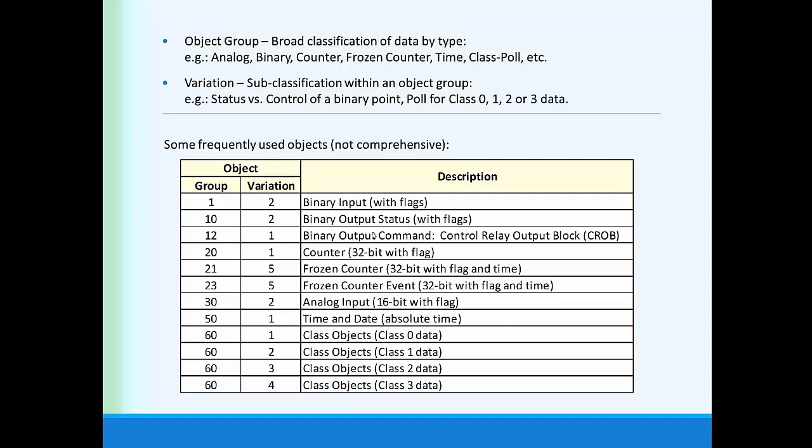So what's a class 0 poll? An outstation or a meter or an IED will have, basically, a meter does kilowatt hours. A SCADA class instrument might do amps, volts, watts, and vars. A relay might have statuses and alarms and targets. But any of those devices has a limited number of objects that are available. And class 0 is basically a way of saying, I want to know what all of that is. It's like the fast meter command: tell me what you've got for me right now.